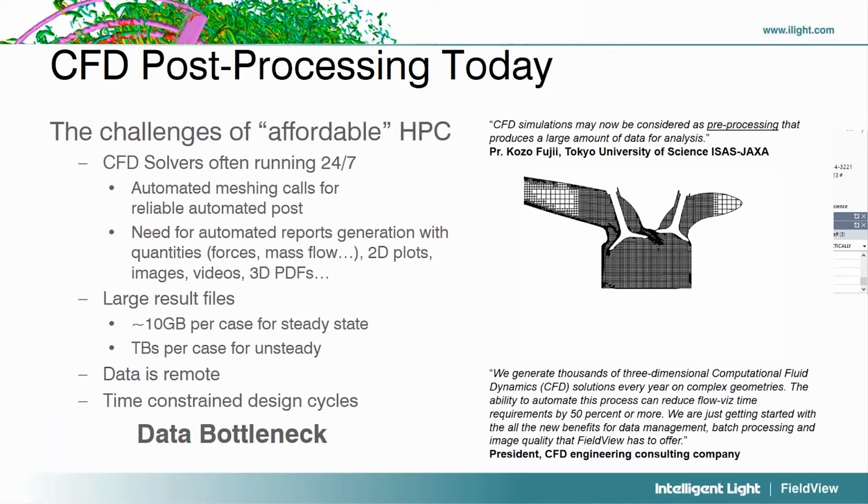Now that people have got rid of the problem of meshing, with high-quality automatic meshing, it's very easy to make a quick change in a Converge input file, rerun Converge in batch for different flow conditions, maybe a different design, and boom, you generate another terabytes of data for a new simulation, and you have all this data that you have to look at.